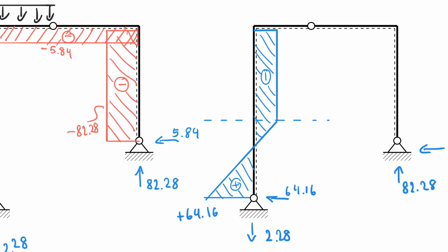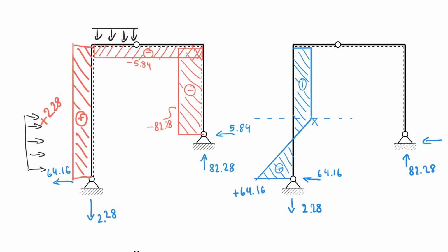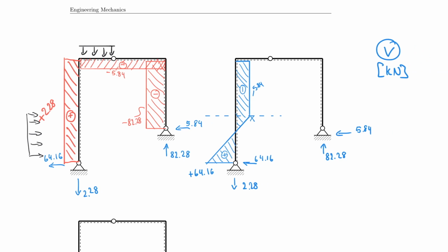And what is my value down here really? It's effectively 64.16 minus 20 times that distance, which also happens to be negative 5.84. So this is negative 5.84. And that diagram was easy to draw. And again, I'm drawing this right now because I already did the cuts and so on. So if you're in doubt about this, feel free to make the cuts. It will always help you.